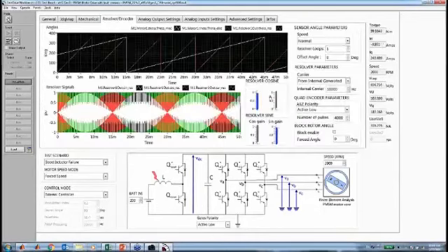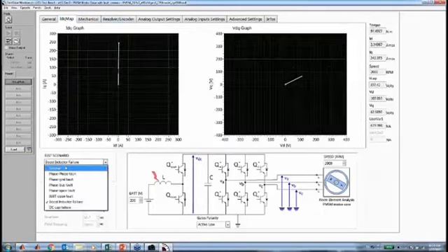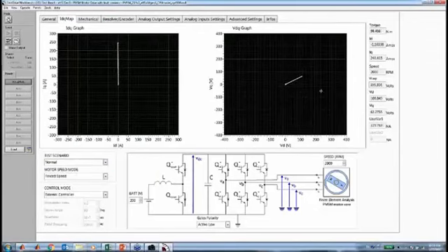We have a pretty good resolver encoder tool where you can modify the gain of resolver sine and cosine, and you can also apply faults to these. So it's a very good tool for testing. After that, we have a good view of VD, VQ applied. Now my boost inductor was in failure mode, so this is why my VD, VQ wasn't very stable.